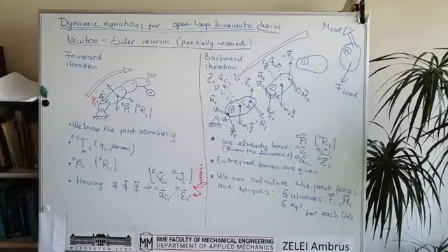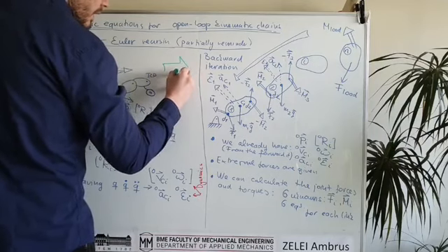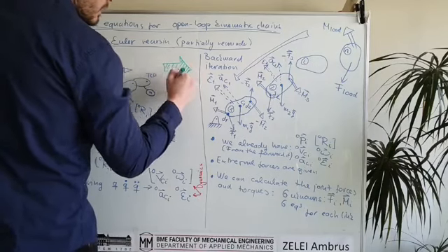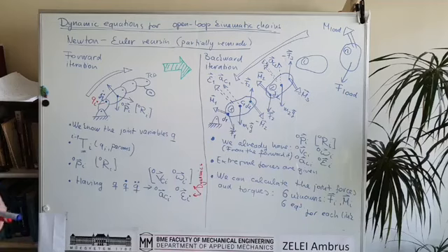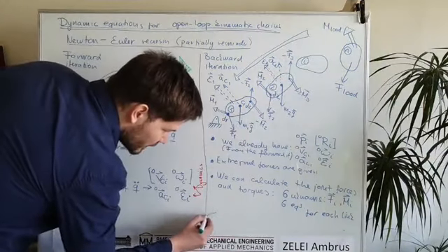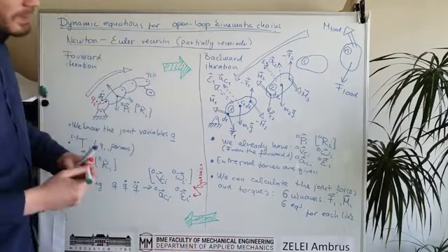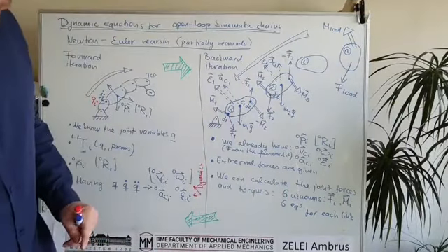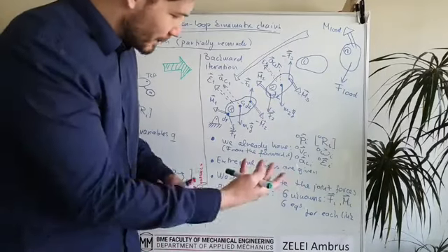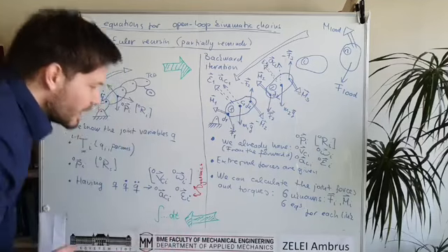And this whole thing is called iteration because we already had this step. So we come from the kinematic calculation, and then we can create the dynamic equations, and then if we have the dynamic equations, we are able to calculate the joint torques and joint forces. And if we have calculated the joint forces, we can calculate the accelerations again in the upcoming time step, and we can integrate our equations.